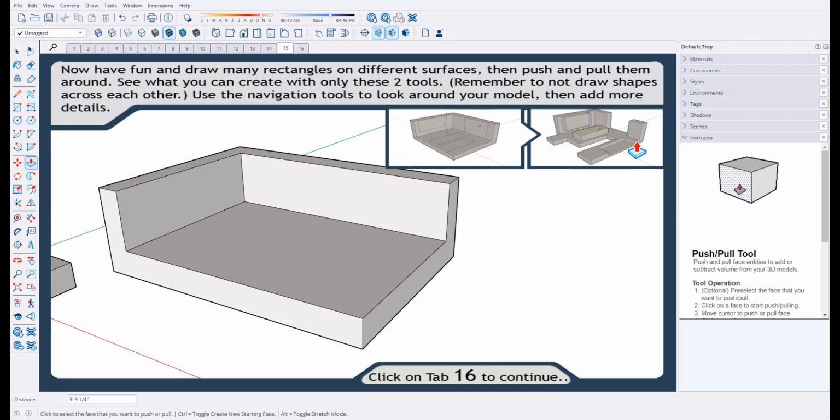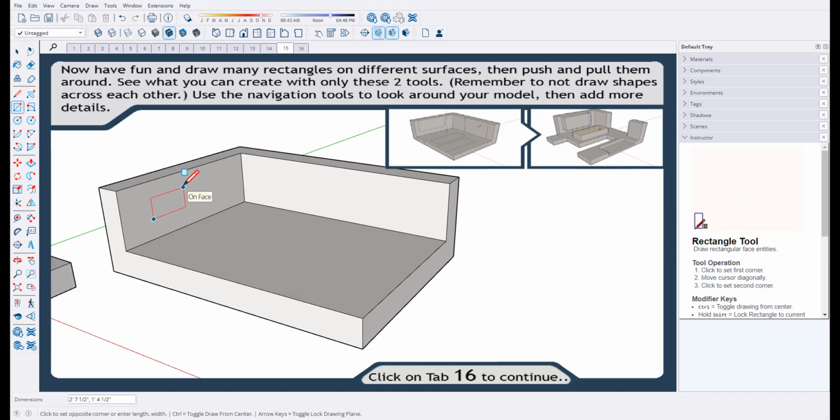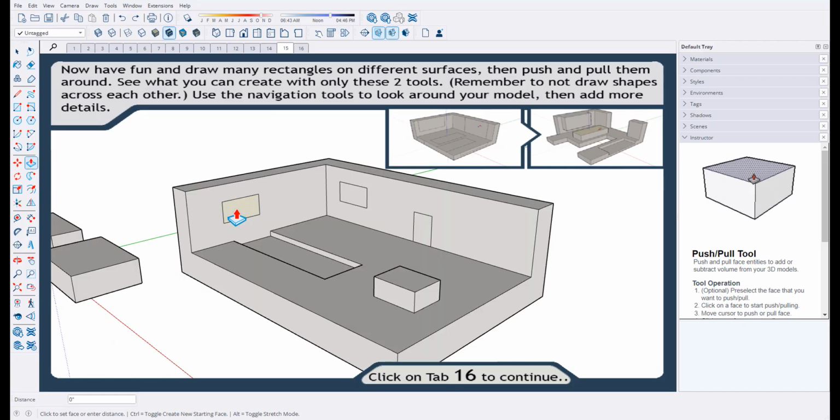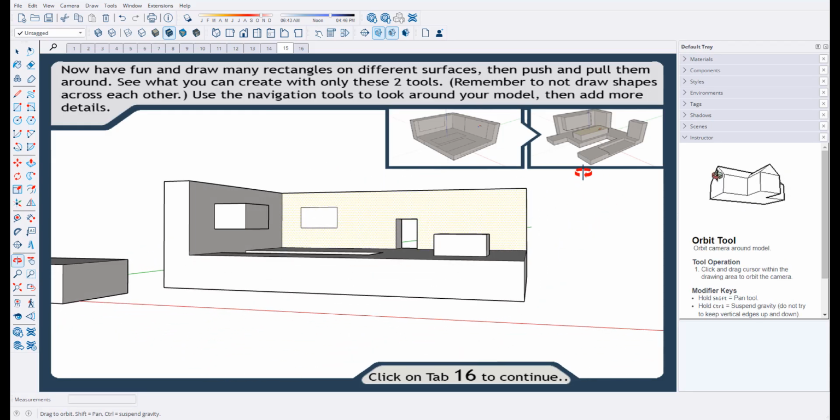And now they want you to make other squares and push-pull them. So go ahead and make other rectangles on the surface, different kinds, coming from the edges. It doesn't really matter how you do this. It's whatever design you want. And then push-pull up or push-pull down. If you click on this surface, and then when you go back, click to this one. You can see I'm still going back over here, but if you click over here to this edge, it'll create a hole.